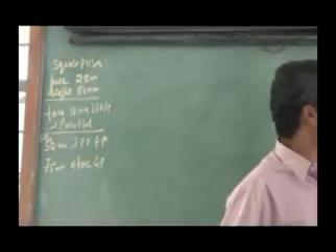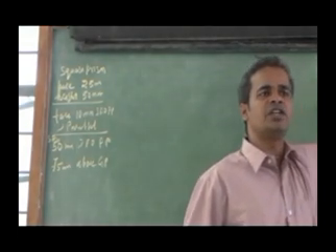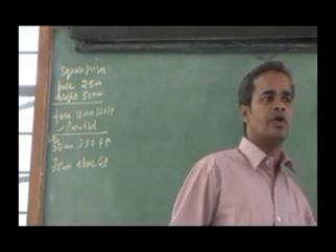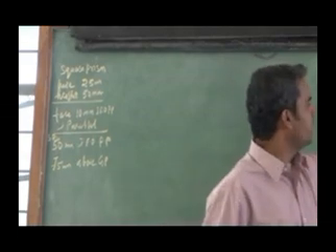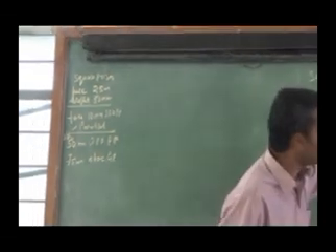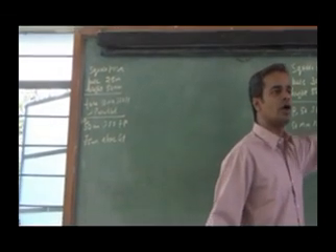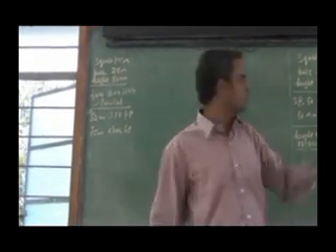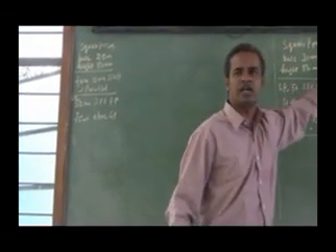So only this square prism will be seen in the top view. The rectangle for the height will be seen in the front view. While drawing the square, 10 mm will be in front of the picture plane. You have to draw the square at 10 mm in front of the picture plane, and the face is parallel. Similar condition, I have to draw it.